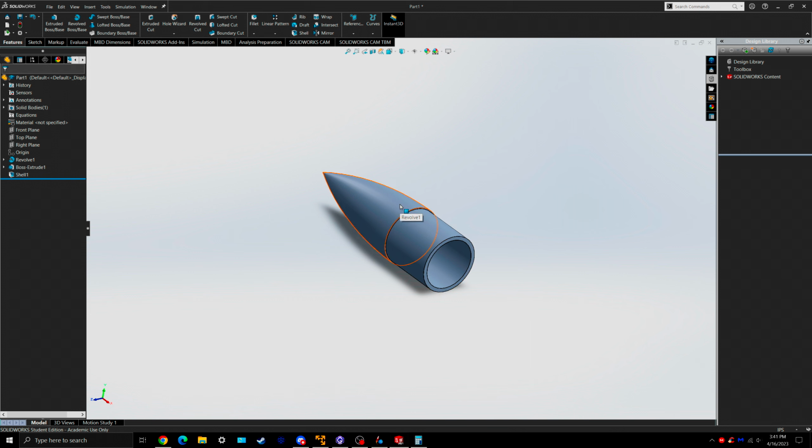All you would have to do then is bring an STL file on a USB to the TI lab. They will be able to do it for you. Those printers are calibrated specifically for nose cones, and they'll probably do a 20% infill, but that should be giving you the perfect nose cone. So yeah, that's how you design a nose cone in Solidworks.